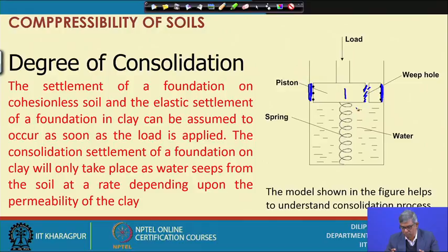the water will be pressurized. That means pressure will develop within the water. If I apply some amount of load P, an equal pressure of the same magnitude will be developed within the water, but still there is no transfer of load to the spring.